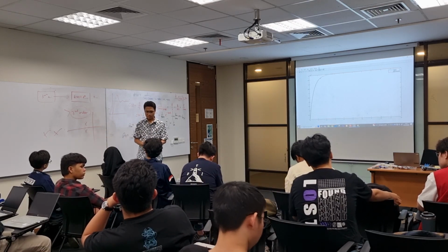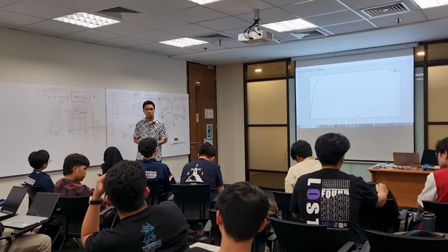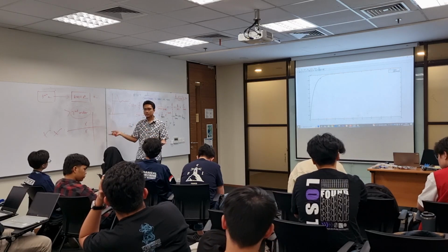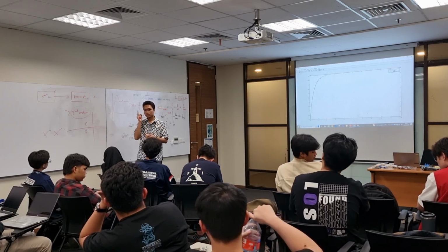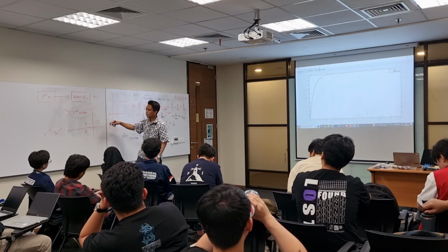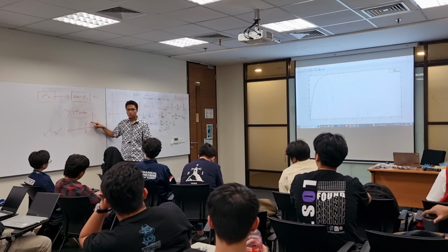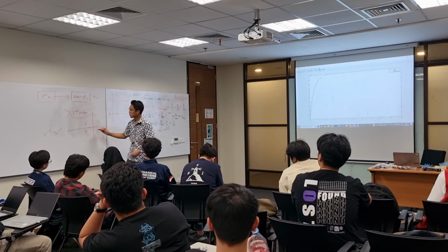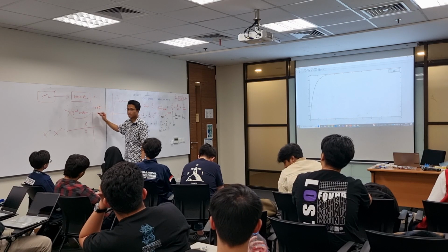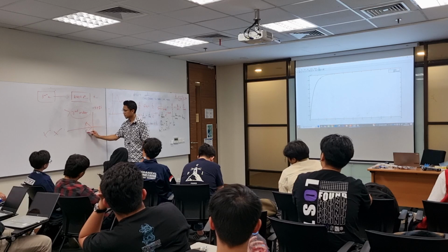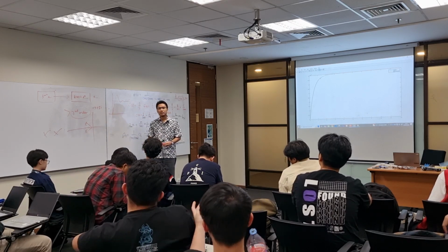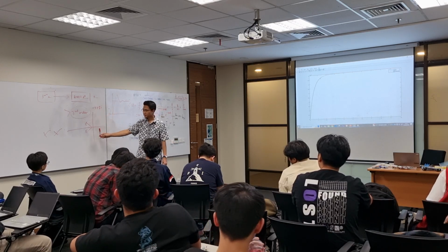So the question is what we want. If your desirable characteristic is a first order system, then your dominant pole is only one. If your desirable characteristic is like this, then you have two dominant poles, let's say -3 plus minus 5i. This is two, right? But they are complex poles, and this is plus minus.